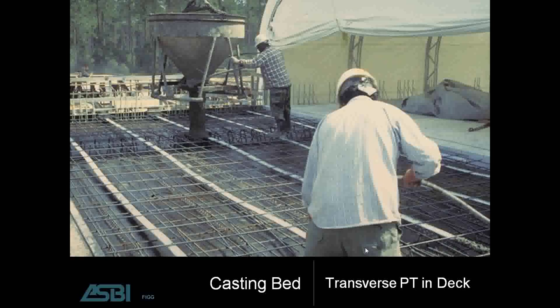One thing I want to point out is the durability of the deck is greatly enhanced because of the top slab. Because the top slab is post-tensioned in two directions, and that is one of the great advantages of segmental, because you do get the two-way post-tensioning, which greatly reduces the cracking that could occur in the future.